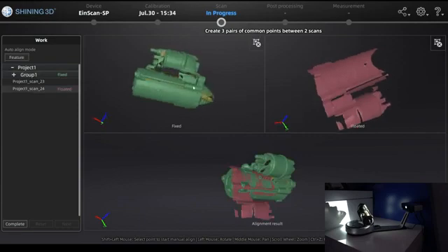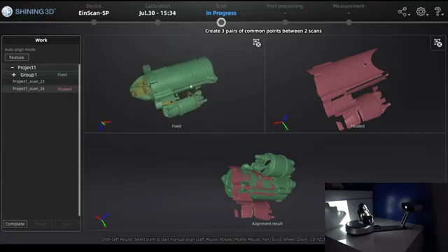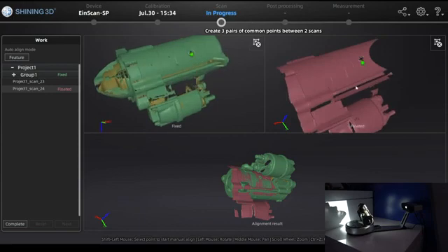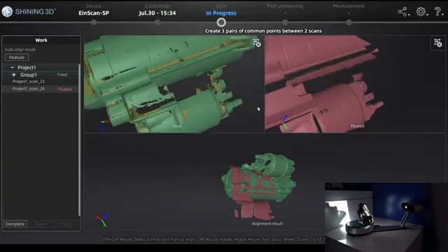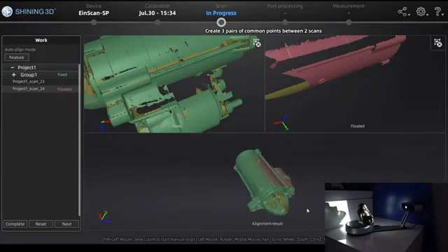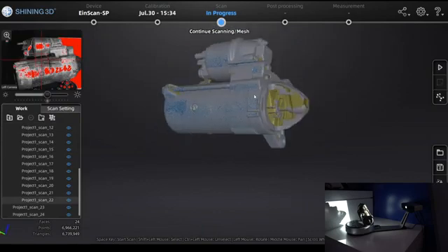You can anytime use the manual alignment function and just choose 3 common points. The points don't have to be positioned perfectly. It's just approximately, the points around these points that they are quite in the same position. And then, as you can see also here from the bottom part, we scanned a bit more. Complete, and then the model looks already quite good.